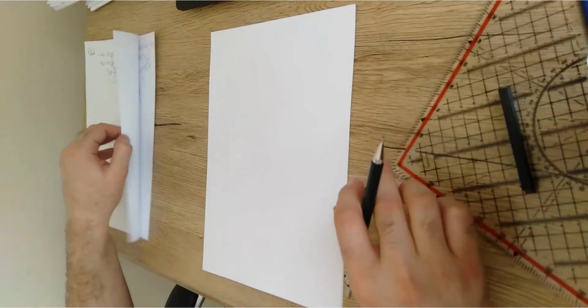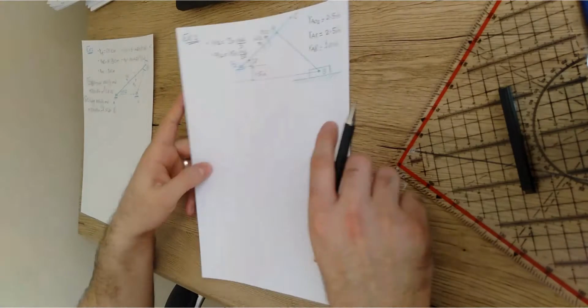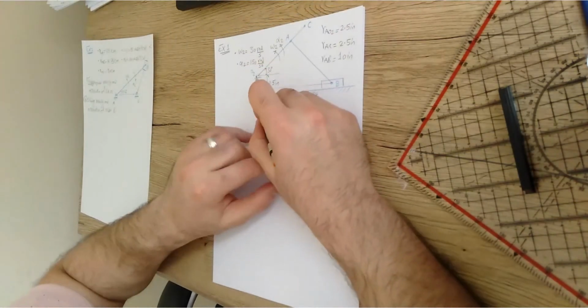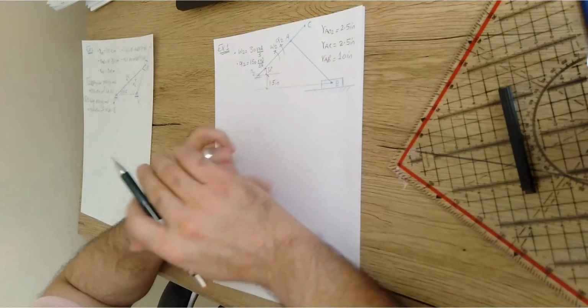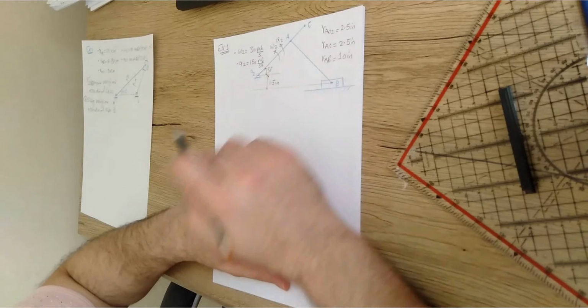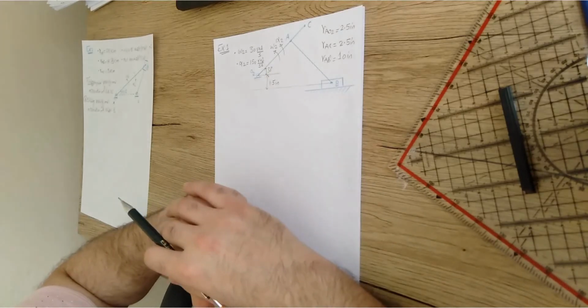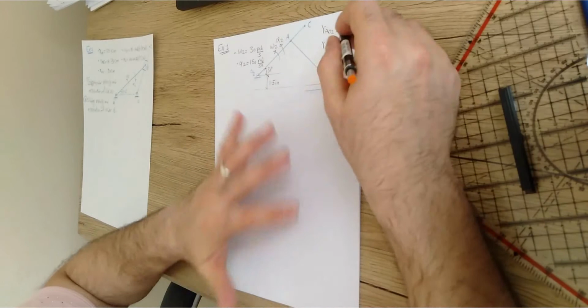So, starting with example 1, it is simply a crank slider mechanism that has the crank O2A, and there is a connecting link which is AB, and there is a slider that slides over the horizontal surface, but there is an offset distance here of 1.5 inches as already given, and this angle is given as 30 degrees, in addition to some dimensions.